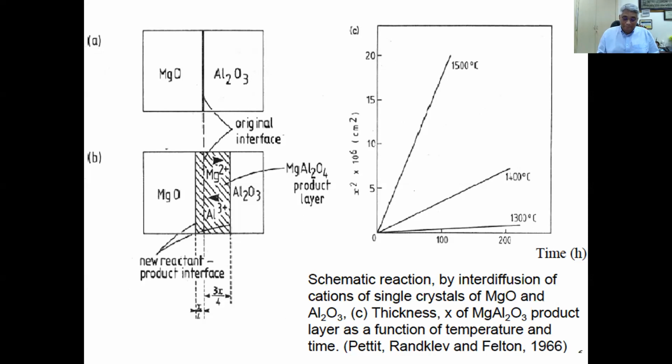And then you're making the diffusion happen. So that's why I said it is so important for diffusion in solids that high temperatures are very important. But let's say a solid has a melting point of only 1000 degrees centigrade. There's no question of going up to these temperatures. So you have to do the heating for a polycrystalline material below 1000 degrees centigrade only. So you can imagine the diffusion rates will become much lower.